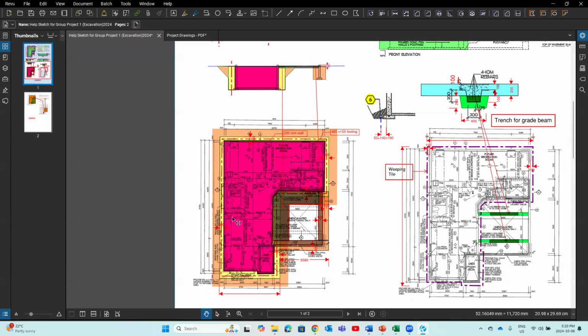If we look at this part, basement backfill, the easiest way for you to do the calculation is to take the total volume of excavation, subtract the volume occupied by the basement. This pink color, you will be able to get the volume for backfill. I think that is the easiest way. Some students say, Miss, I want to do this. Take the volume of this part, multiply by center line length of this. That's fine. But if you do that, pay attention to this here. You have extra backfill here, and you have a little bit extra backfill there. That's what you need to pay attention to.